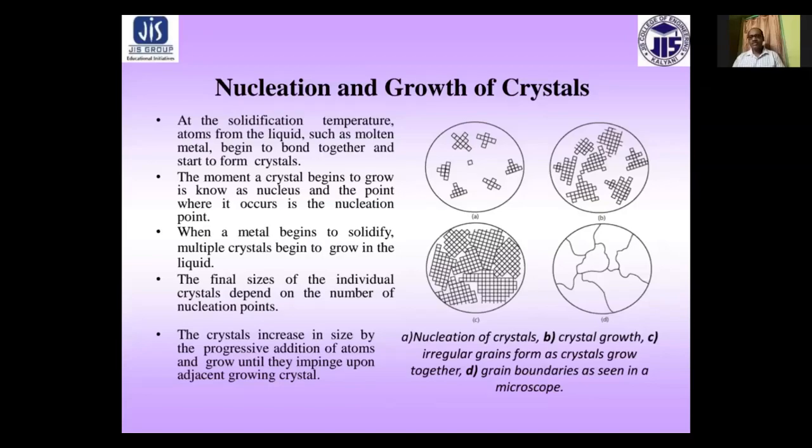When the temperature is lowered, the vibration of atoms gradually decreases, increasing the chance of survival of the small clusters of atoms, and therefore the critical size of the nucleus decreases with decreasing temperature or increased degree of undercooling. Hence, at lower temperature, nuclei become progressively smaller in size, but their number greatly increases.